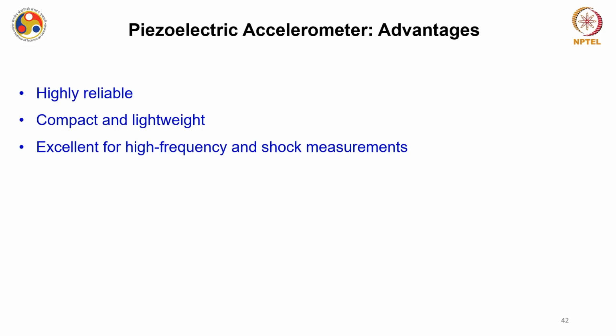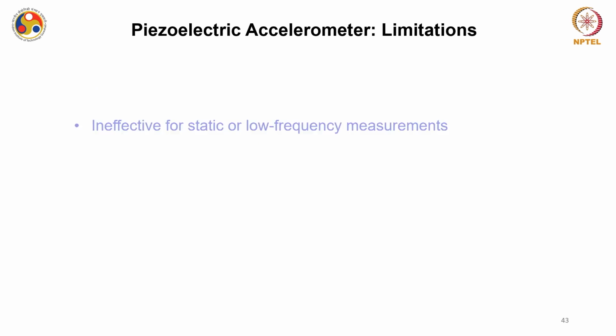There are a number of advantages associated with the piezoelectric accelerometer. They are highly reliable, compact and lightweight, and they have excellent high frequency and shock measurement behavior. They have a long operational life as well as a longer shelf life.